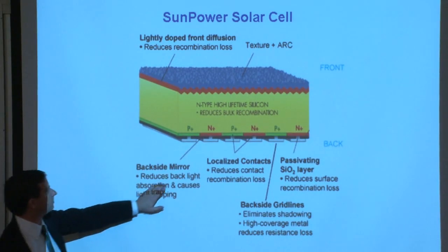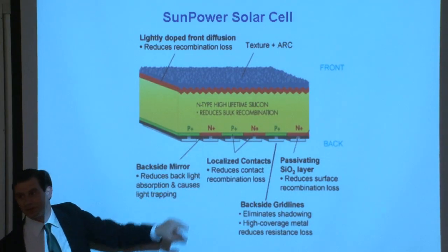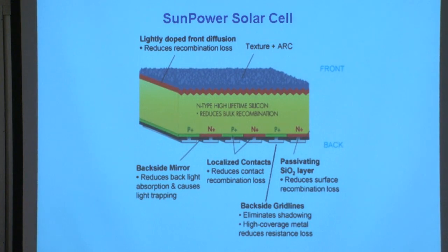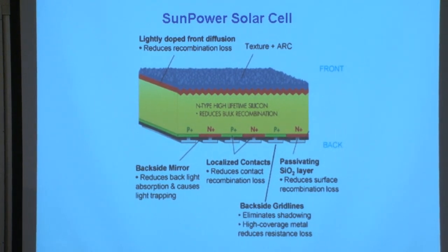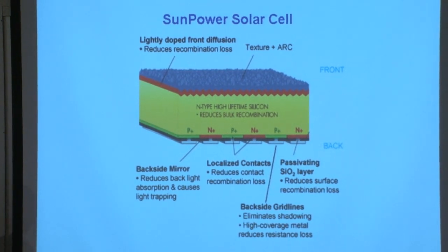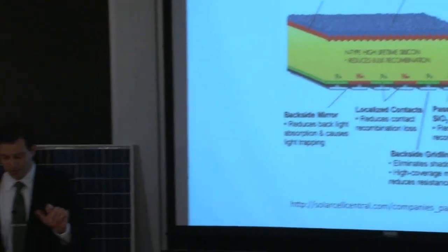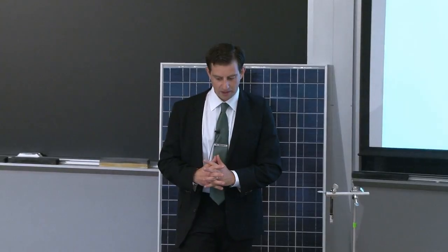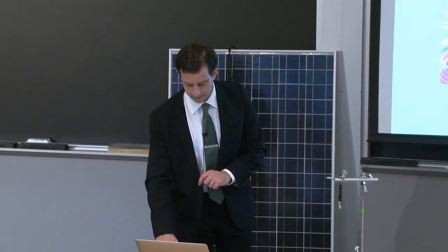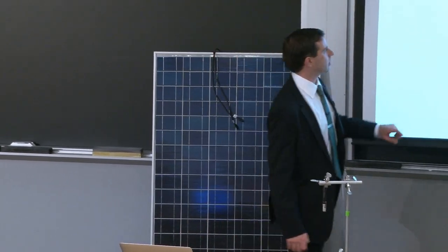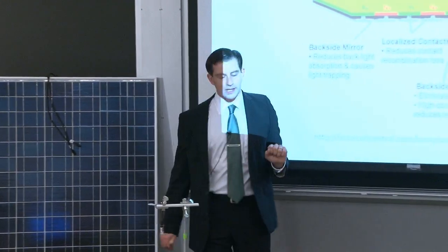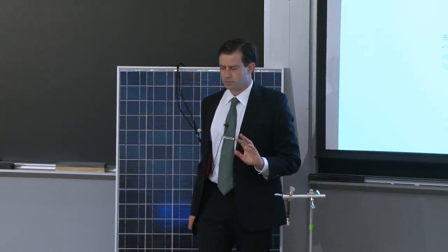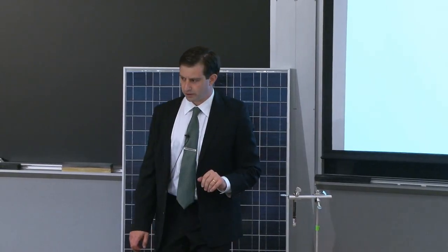They definitely take good advantage of it. Where you have your metal, you're going to be absorbing the light, or you have a higher probability of absorbing the light than you would if you had a dielectric semiconductor interface. So the device design can get pretty complicated for these super high efficiency devices, and they're worried quite a bit about light trapping, other things as well. How efficient is that one been? This one right here, in the lab, 24.2%. In commercial production, 22% and change, 22.4, I think.